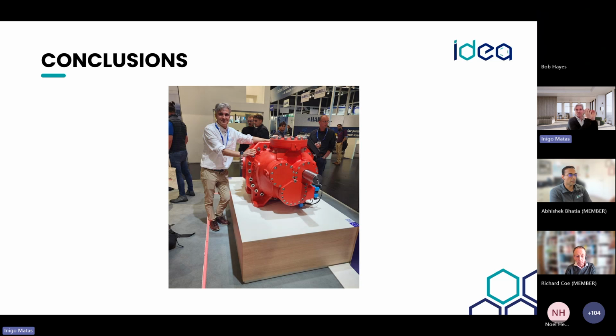As a summary, we have seen how a heat pump, like this beautiful machine that we can see here on the screen, can be integrated into an industrial process. Heat pumps are a strong option for decarbonization and increasing process efficiency when the right heat source and heat sink are available. The key point is to understand the process in detail, as we have said a few times. Without accurate temperatures, duties, load profiles, and knowledge of the operational constraints, it's impossible to design a system that makes the most of it and is reliable.